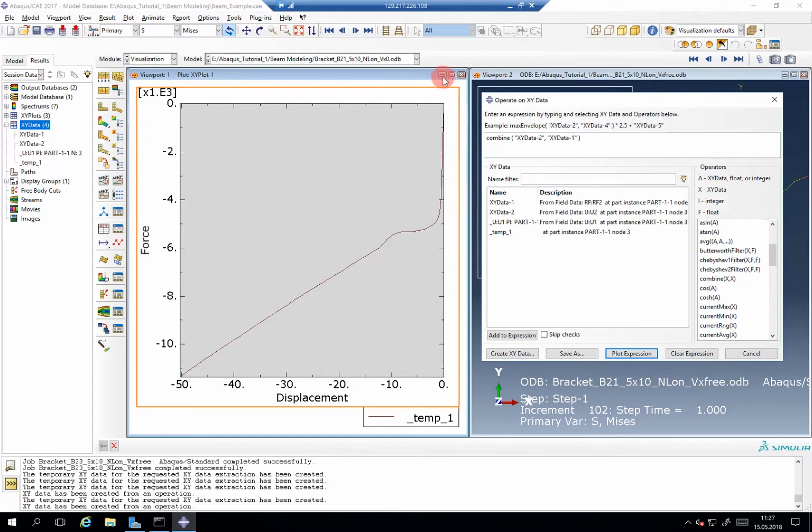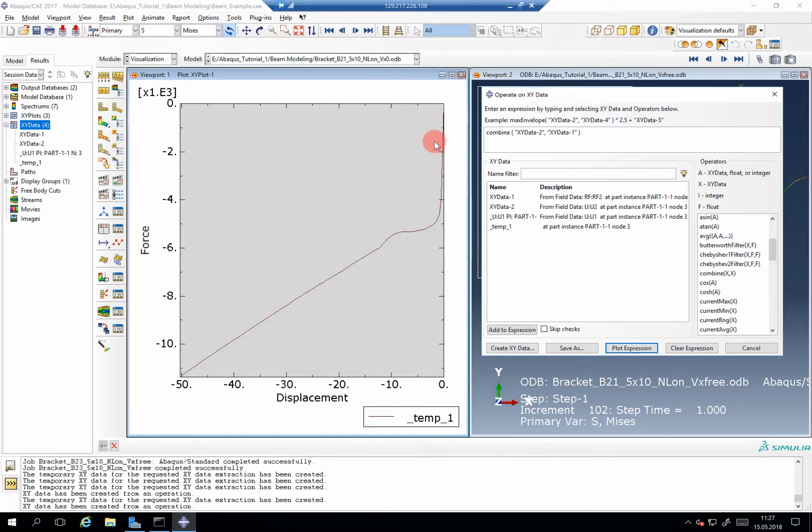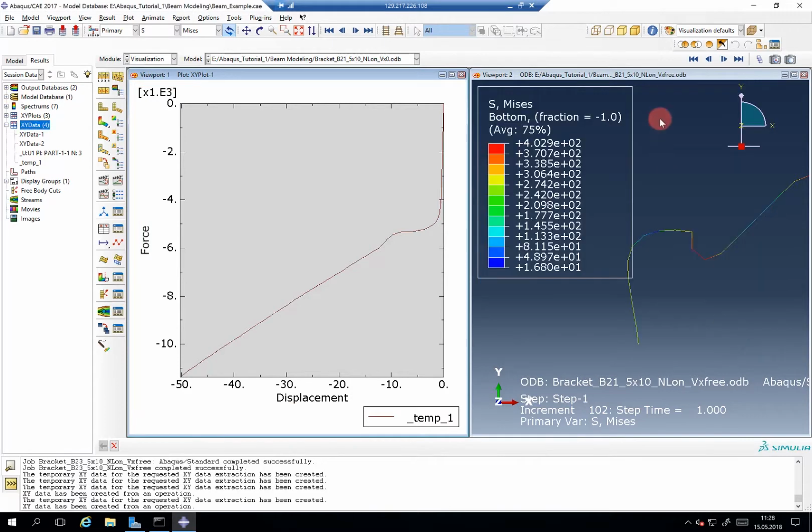So in the beginning, there seems to be a very steep increase of the force versus only a small fraction of displacement. And later on, it goes to a linear. But you can definitely see some nonlinear effects in this area here. And you should definitely uncheck NLGeom and see how in this area, for example, the force displacement diagram changes.